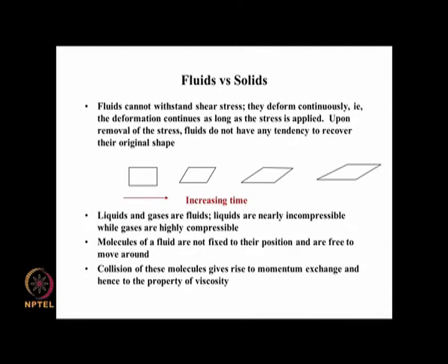So, let us first of all establish the difference between fluids and solids. We have an instinctive feel for what fluids are and what solids are, but in a technical way we can say that fluids are those physical substances which cannot withstand shear stress, and by this we mean that they deform continuously, that is, the deformation continues as long as the stress is applied, unlike the case of a solid which deforms.